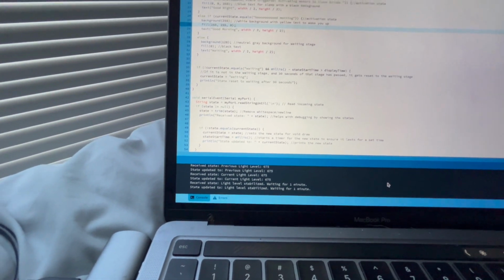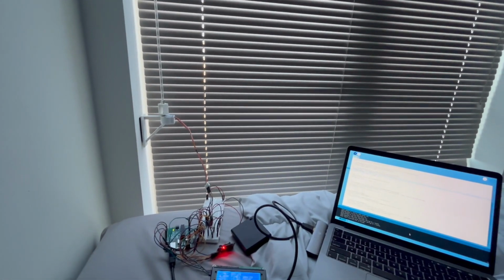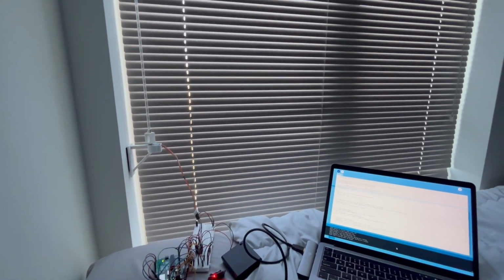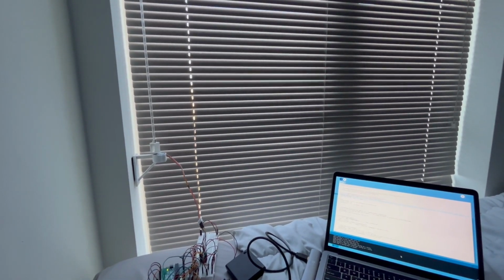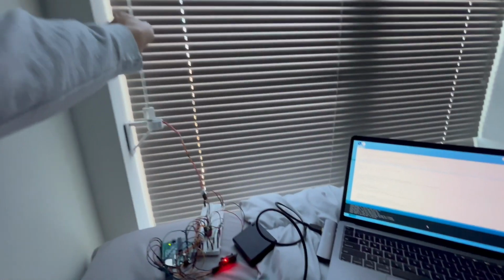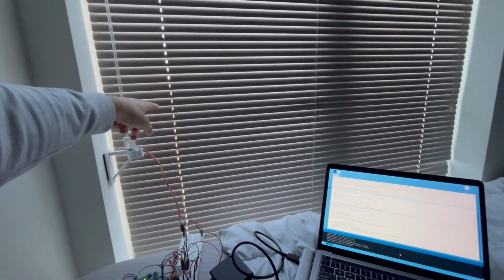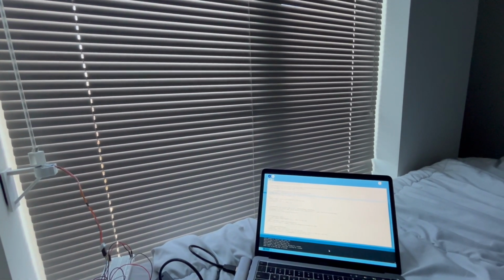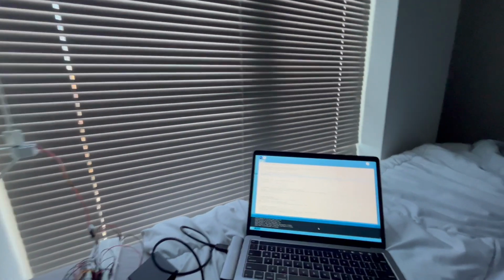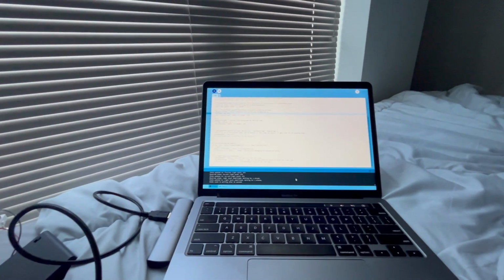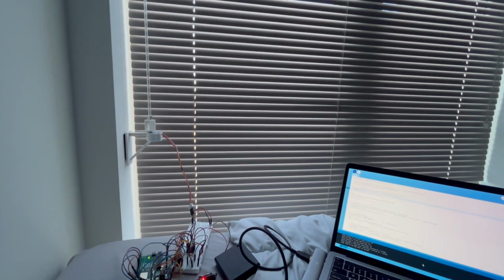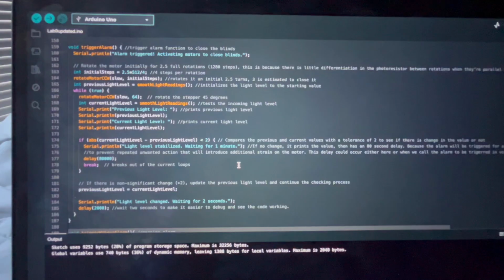And so essentially why it does that is it's calibrating, so when the motor starts to stall, when it's fully twisted, like no matter how much you twist this one right now, these are at their max angle. So when that begins to stall, the photoresistor senses it by detecting that there's no light changes, and that allows the motor to stop when it's fully closed.